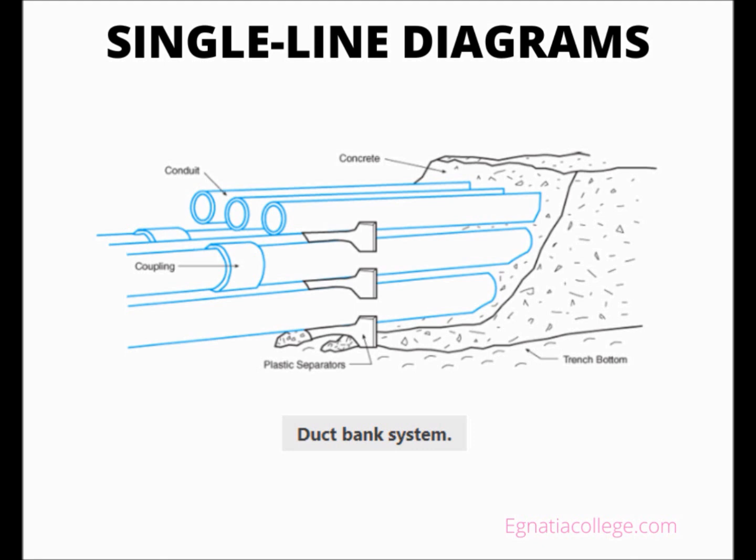National Electrical Manufacturers Association, NEMA, generates specifications that are recognized as design standards for electrical boxes, devices, and equipment. NEMA 3R is a rain-tight designation. The new portion of the single-line drawing shows the electrical distribution to be installed in this school edition. The feeders for the new elevator, electrical panels L10.